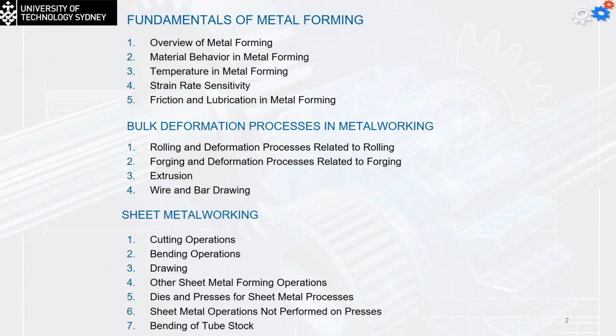Sometimes it's a net shape process. That's when we can take the part and use it directly. And that's usually very rare. Usually we need to do an extra process on it to make it useful. Among these processes is deformation, or forming.